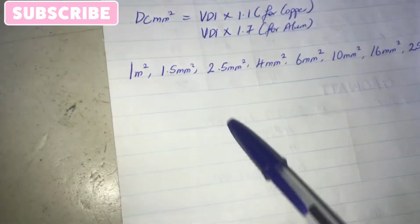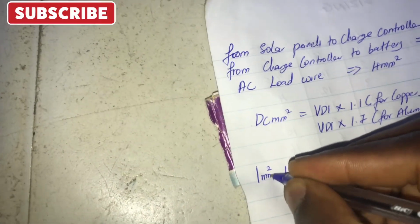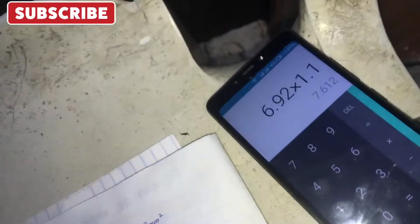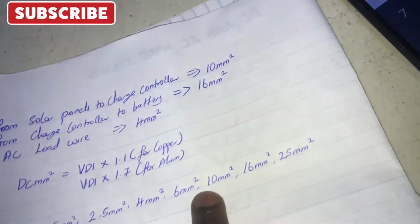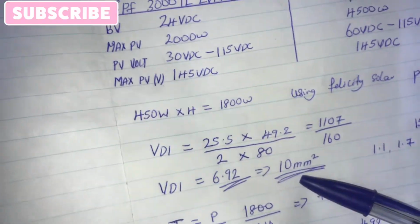And here I've just written out the sizes of wire we have: 1 mm, 1.5, 2.5, 4 mm, 6 mm, and so on. Here we have 7.6. After 6, there is no 7, there is no 8, there is no 9, all we have is 10 mm. So it has already passed 6, so the nearest one we have is 10 mm, which is still the same thing we got, 10 mm.